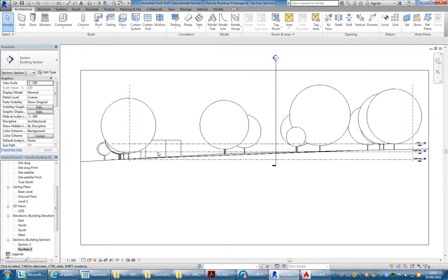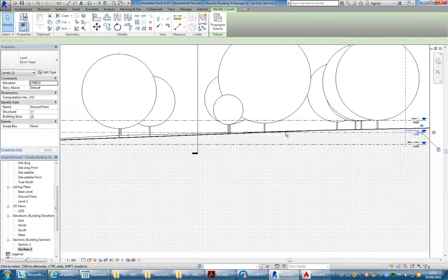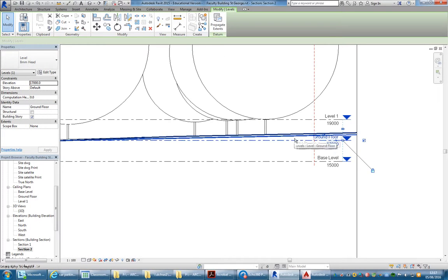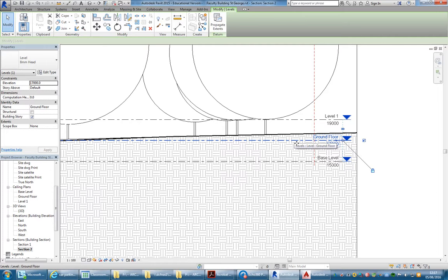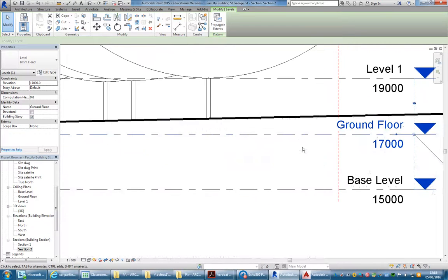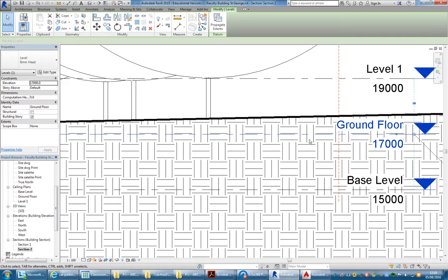But if you want to have it closer to ground level, then you'll definitely need to excavate and have the building set into the ground. And then if you're going to do that, you'll need to think about having retaining walls at the back. And that might not be a bad thing either. So again, these are the sorts of design considerations you'll need to consider almost from the beginning.